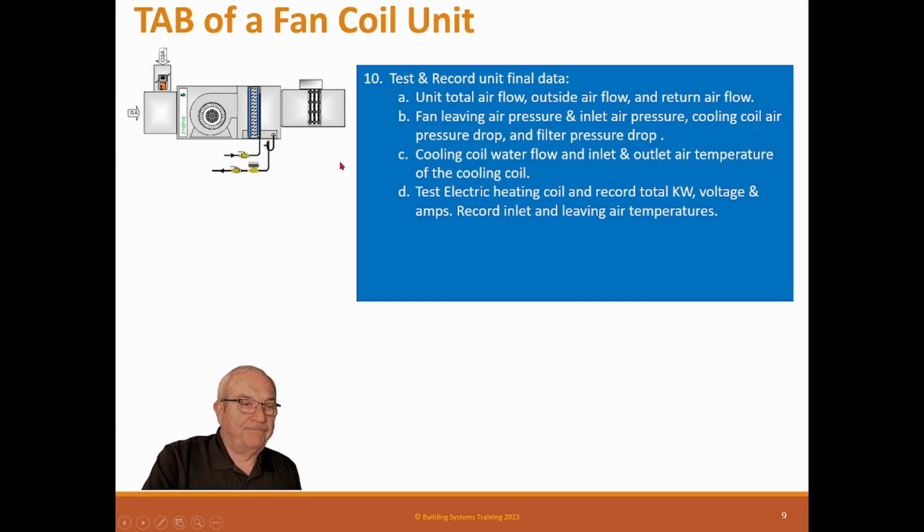By the way, some balancers that have low ethics, I've seen them try to use this to say that they balanced the chill water, and this is what it is, or vice versa. But if an engineer knows what he's doing and looks at the report, he can tell you faked it. The reason is it's very difficult to take these readings in an instant in time. For it to come together mathematically, it has to be instantaneous. You can't take a reading on a coil and wait 5 minutes and take a reading of water. They won't be the same. So you can try to push that kind of stuff, but it doesn't really work if you know what you're looking at.